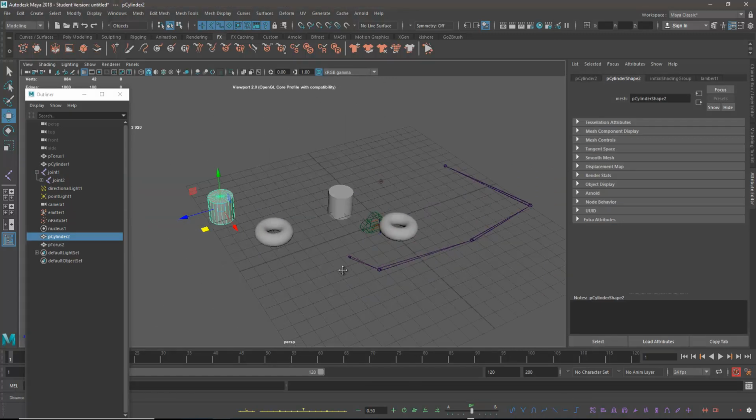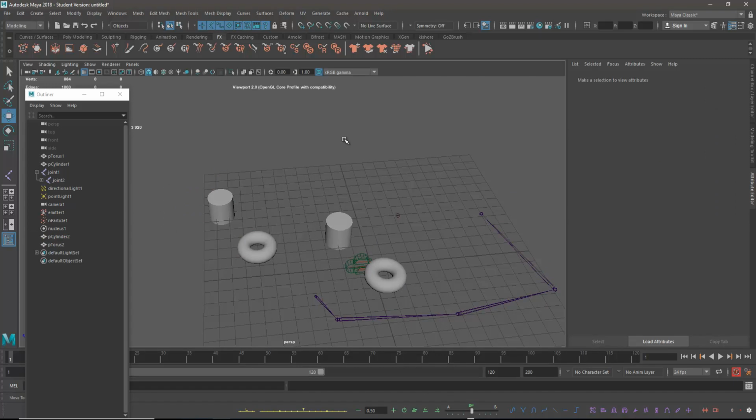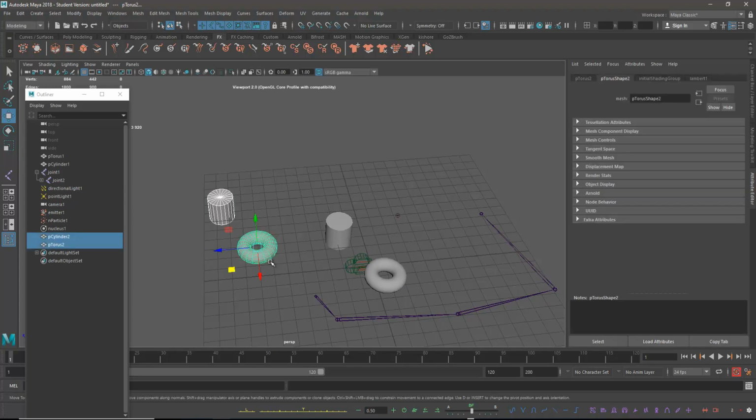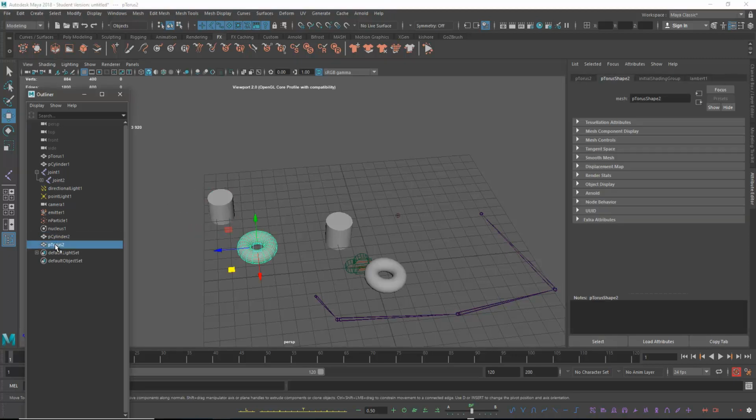See here, remember we have discussed grouping. Select these two geometries and press Control G, and that will become a group, right? This way we can group, or you can see the cylinder and tires. Here we can hold the middle mouse button and drag over, above the cylinder. See here, we can navigate like this also. We can select the particular torus, and we can put it in the middle of the two lights like this.